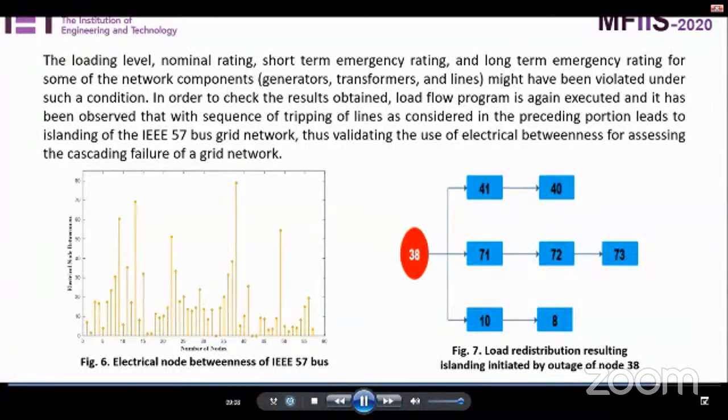During islanded operation, the system is divided into 2 or more sections, and each section may tend to have an overvoltage or undervoltage problem depending upon the amount of generation available in each section.